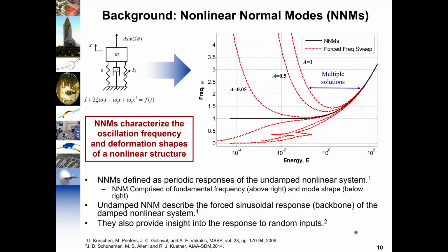So this leads us to a new way of seeing nonlinear systems. And it's to look at the frequency and amplitude or energy. And Rosenberg in the 60s pioneered a definition of a mode that allows for including both of these. Basically, you can think of a nonlinear mode as any solution to the undamped, unforced equation of motion.